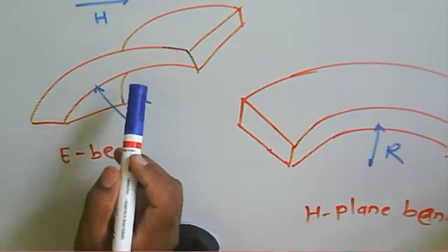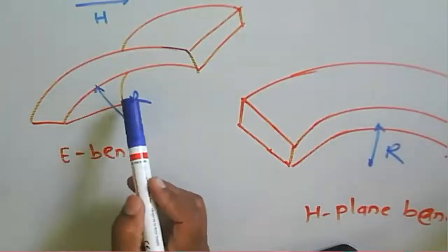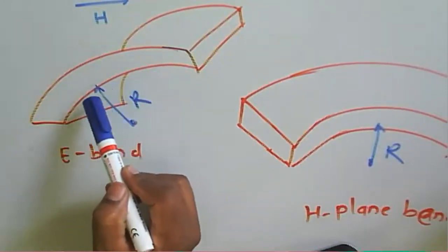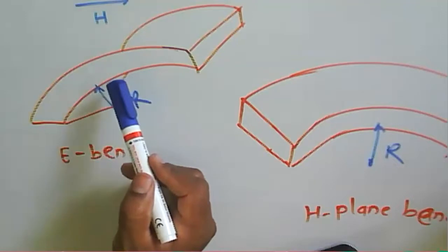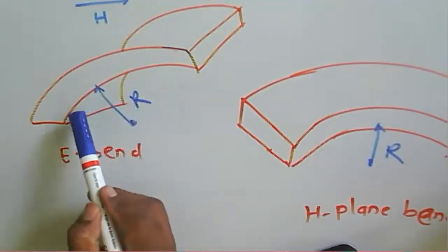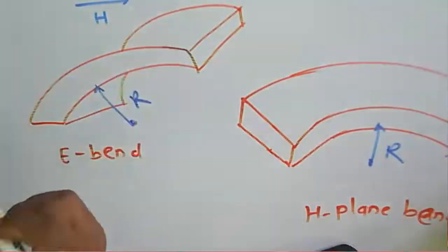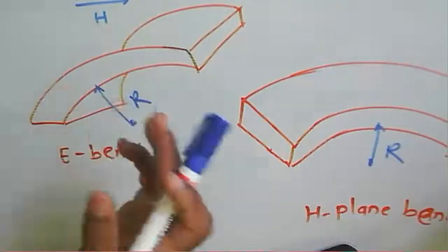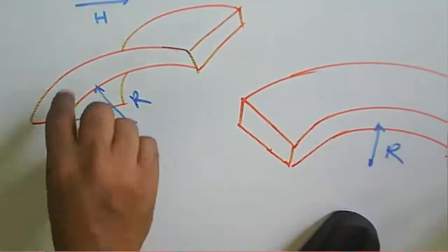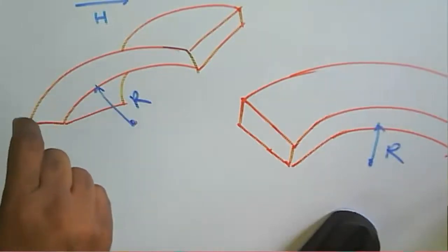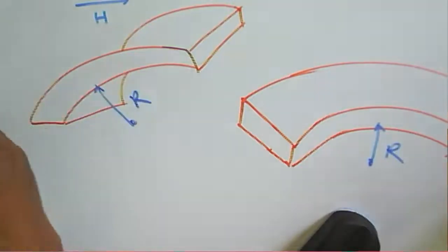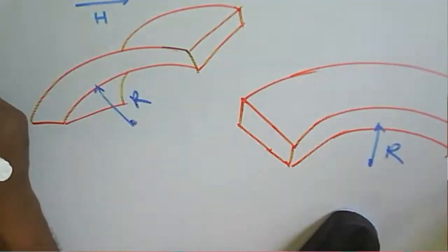The SWR, or discontinuity, occurs because of that particular bend. What happens is that the group velocity will be changed depending upon the path. That's why there will be reflection at that particular bend, or when we join two waveguides, power will be reduced. So we need to find out at what particular value of the radius that bend will produce a low value of SWR.